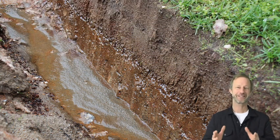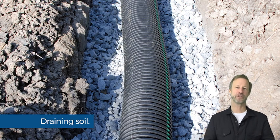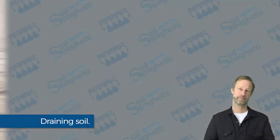Now, let's get to talking about draining soil. The standard assembly of draining soil uses a large diameter pipe with rows of slots cut through that pipe. The pipe's installed in a trench 30 centimeters or 1 foot wide with a 5 centimeter or 2-inch layer of drain rock below the pipe, followed by the pipe placed in the center of that trench and then filled with drain rock to a height of about 30 centimeters or 1 foot. Backfill material is then placed over top of the assembly.